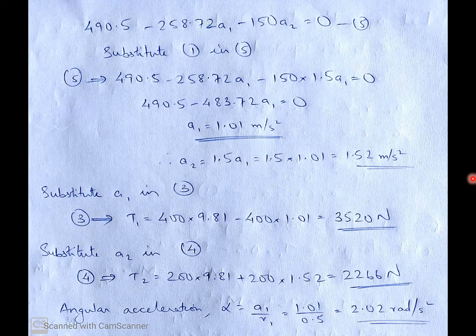So that's all about rotation under a constant moment. It is just similar to what we have seen in motion of connected bodies. Along with the motion of connected bodies, here in this module, there are two more equations to find the torque. Torque is equal to I into alpha, and torque is equal to force into distance, where force means tension and distance means radius. Solving those two, you will get the tension in the string, and you substitute that tension in Newton's second law. So this is the method to find the rotation under constant moment.